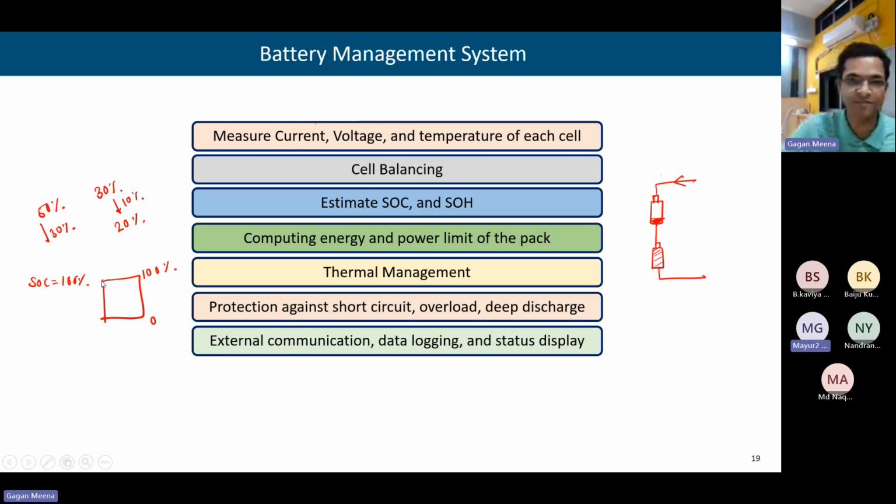You mean to say the end cell voltage kind of thing? Like up to what lower voltage the cell can go? In that sense, say the conventional cell is 3.65 volt per cell I'm talking about, and say I have more experience on nickel, cadmium, and lead acid. That's why I'm asking this. Lithium ion, I have little experience. So in nickel, cadmium, or lead acid, there's an end cell voltage beyond which you discharge, then you may deep discharge the cell, and the cell may not come back.